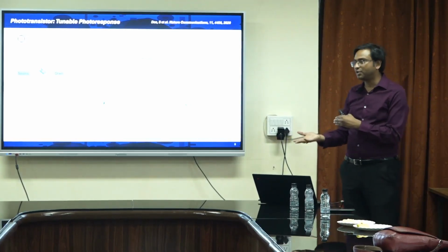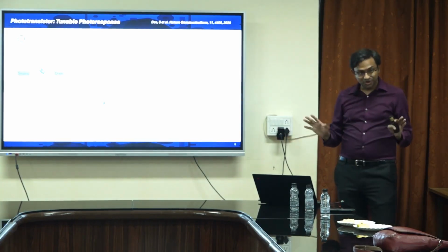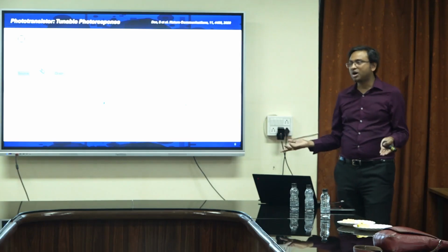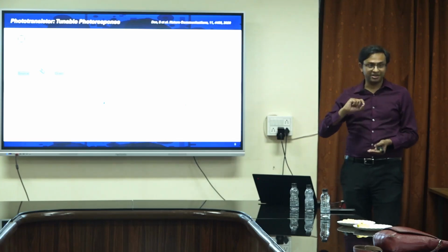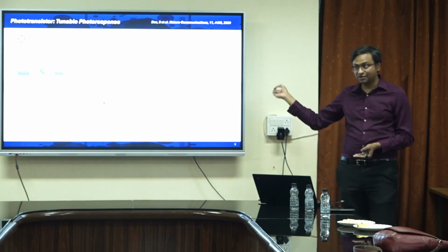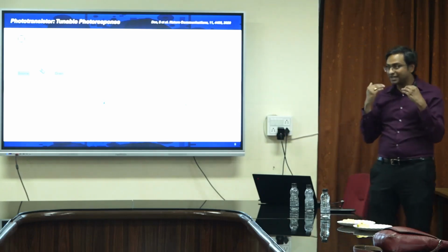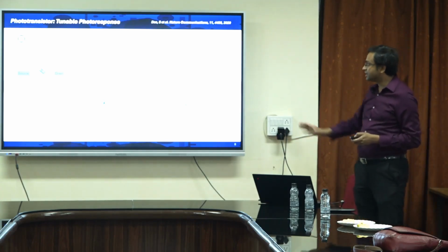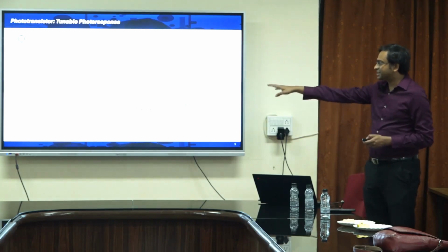So ideally, if I want to use it as a photodetector, here I can tune the dark current, which I cannot do for a photodiode, because for a photodiode, whatever the reverse bias p-n junction diode current is, that is my constant dark current. In a transistor structure, I also have the knob of controlling the dark current, and therefore the responsivity and detectivity. So I can bias it at different regimes, as I will show you, for low light and for high light, almost like your eyes adjusting to the brightness around you, right. That's the advantage of using a phototransistor, and you can subtract the photocurrent between the two.